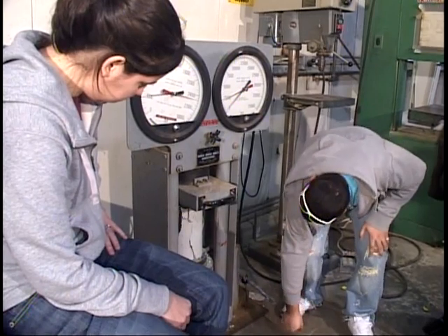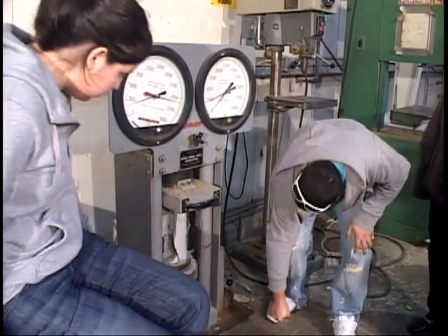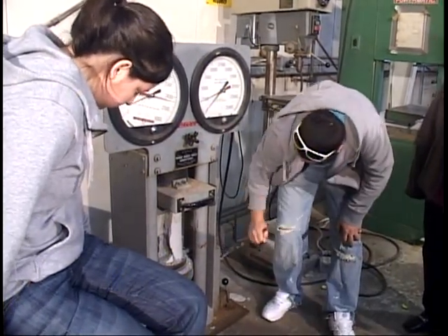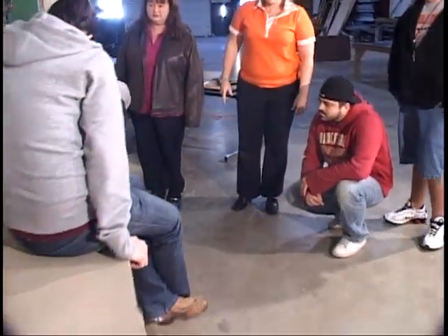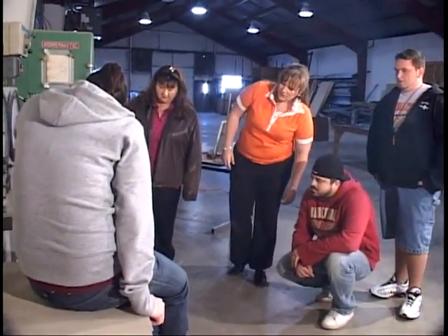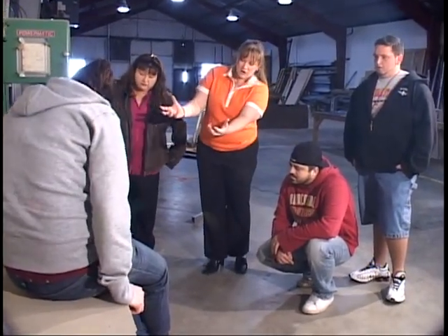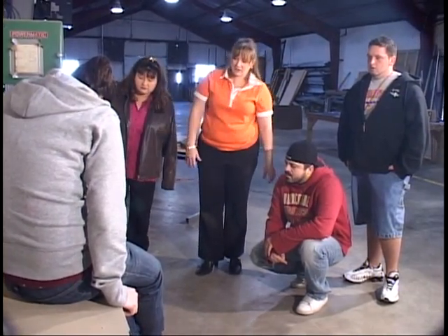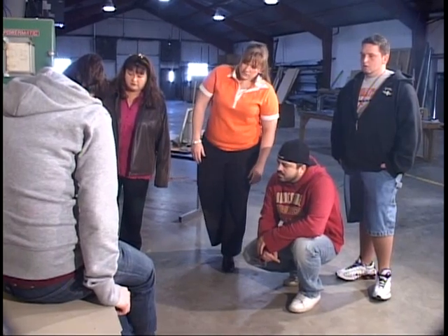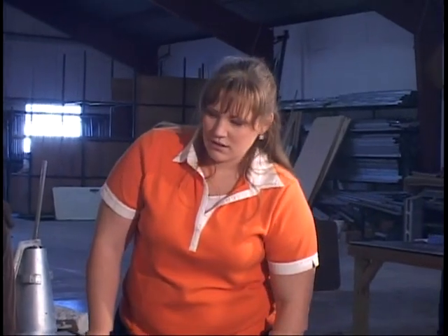So why does it start spalling like that first? That's just the way it breaks. It just starts falling apart. Usually there's imperfections in the surface, and that's where it's going to start to want to break first. Is that all it's going to do? It probably will keep going. You can see after the edges fall off, it doesn't have as much area to load anymore. So it's just going to keep breaking what's left. Just falling apart, crumbling. Yep.